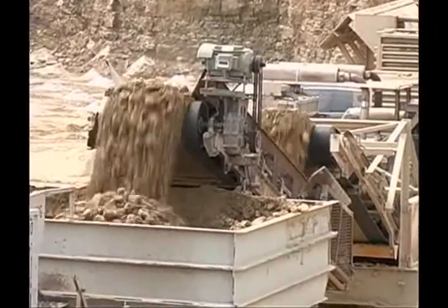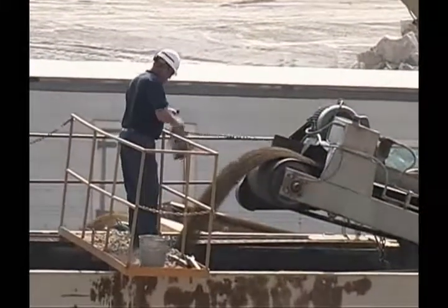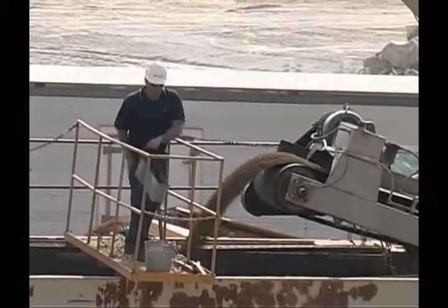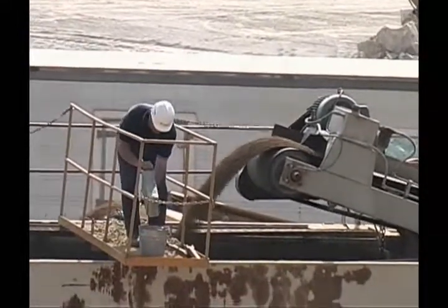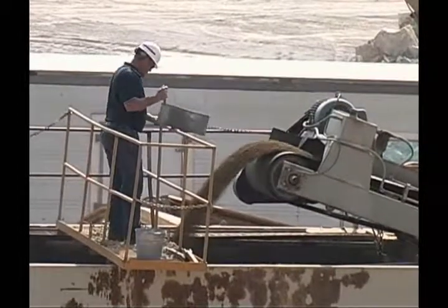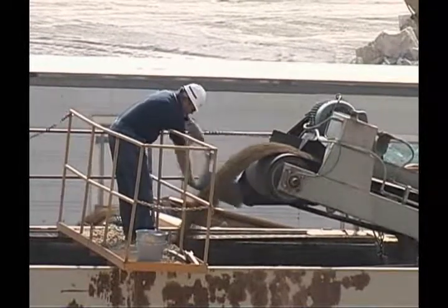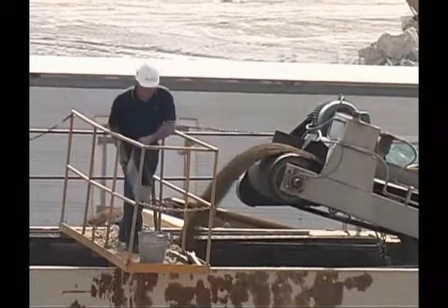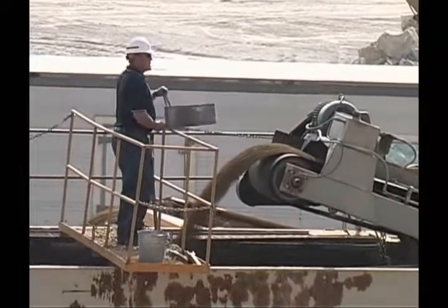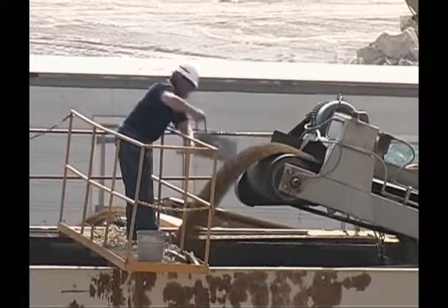crushing or screening plant. Locate the recommended sampling area, being sure it is in a safe location with safety rails and guards in place. Using your sample catcher, swing the device through the entire stream of material, being sure to get the complete flow. Pass the catcher through the material quickly to avoid overflowing the device. If this should occur, discard the increment and obtain another increment. Continue this procedure a minimum of 3 times. More increments may be needed to reach the minimum sample size.